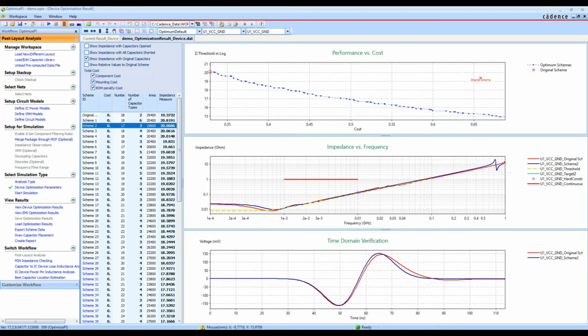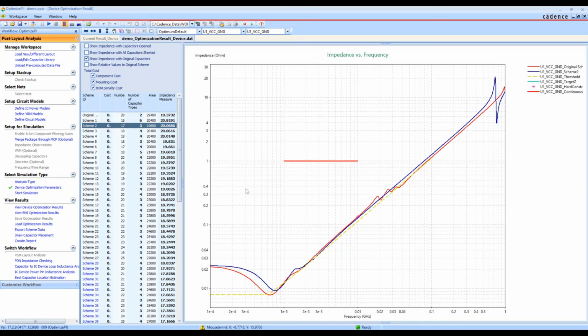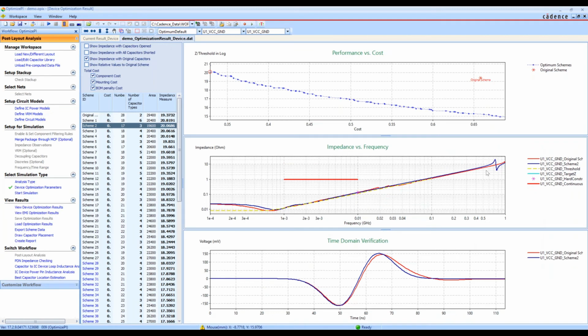So I'm paying almost half what I did for this one, and I'm getting nearly the same impedance value. If you're optimizing for cost and your quality was good enough before, you can now save 30 cents on every board implementing this type of scheme or capacitor scenario and get pretty much the same results. The red here shows your original value, and the blue, I'll zoom in on this, shows your new decoupling capacitor value. This could be a threshold that you want to make sure you don't exceed, and you can take a look at your results here.